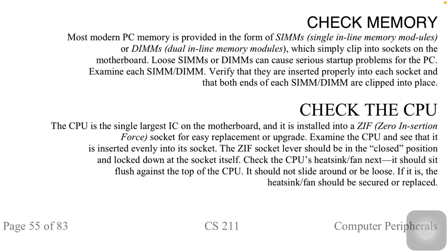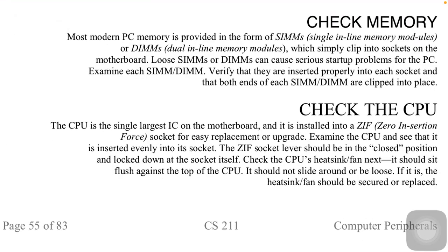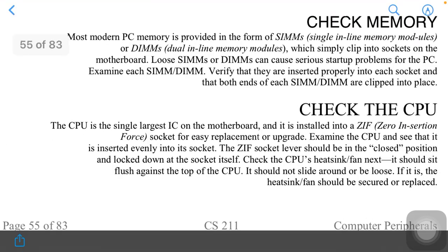Although in some cases the fault from RAM will make a particular sound. We did that in the other year, some semesters back. There are many signals, symptoms, sounds, beepings that have different meaning interpretations. So you can check the RAM. Is it well planted? When you are planting the RAM, you should hear a clicking sound.